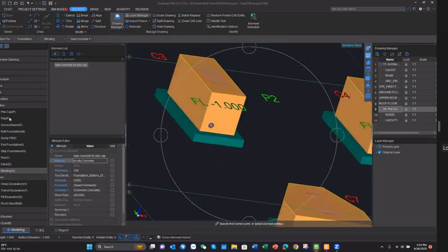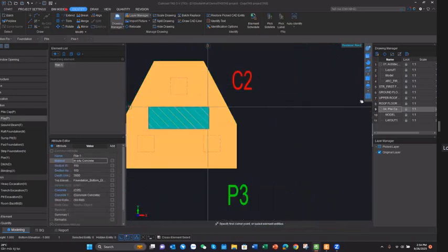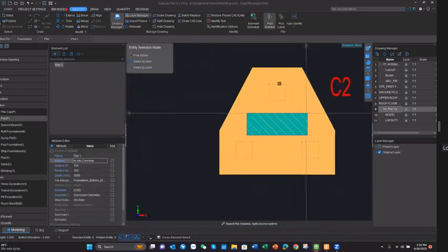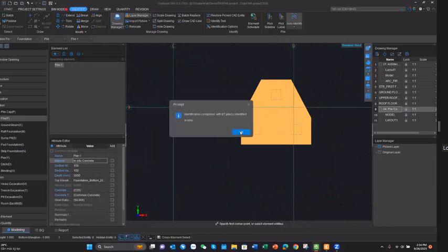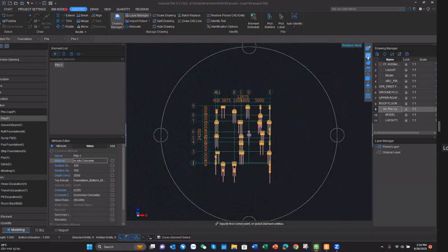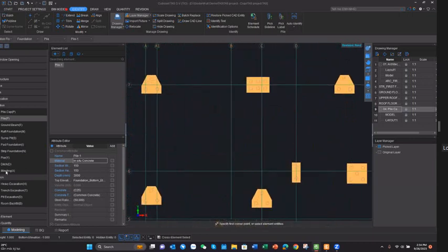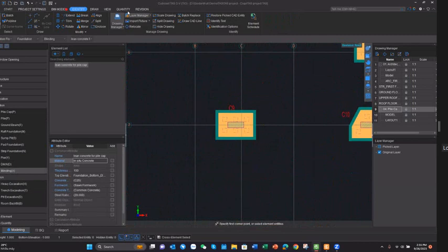And also we have the pile here. So I choose the pile, use the big slide, pile slide, and confirm. The pile doesn't have a label, so I just click auto identify, and then 87 piles are identified in total. Now you can check in the 3D model. And after we have the foundation or link rig, we can also do auto excavation.